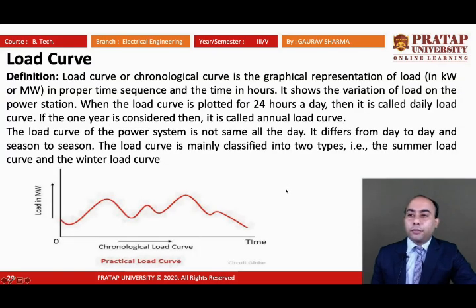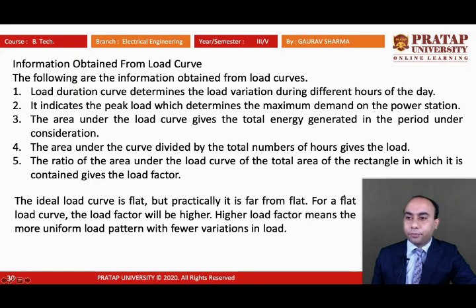The load curve or chronological curve is the graphical representation of load in a proper time sequence against time in hours. I already told about the load curve, it is the same. The load curve tells us the load variation during different hours of the day. It indicates the peak load, which determines the maximum demand on the power station.